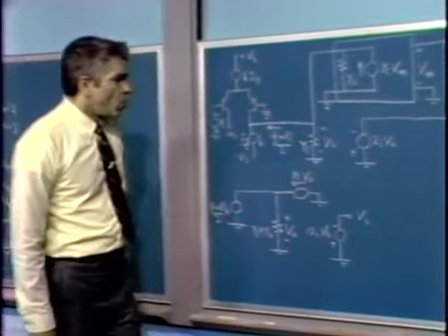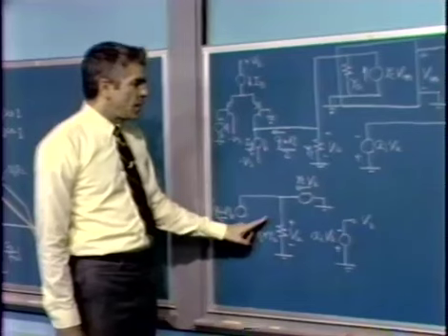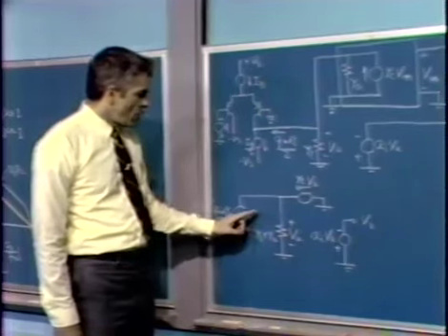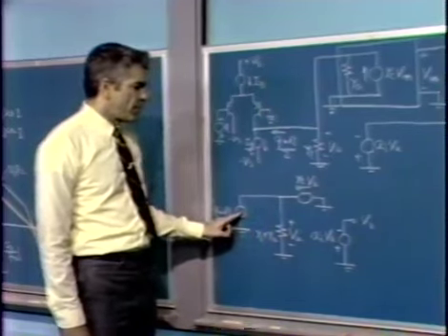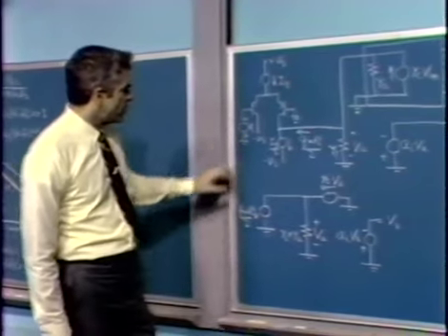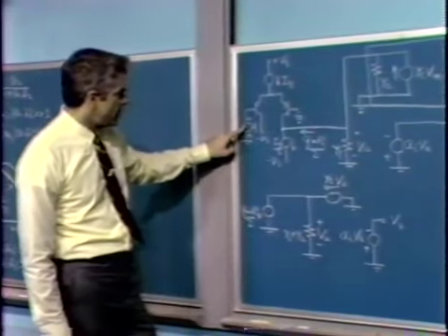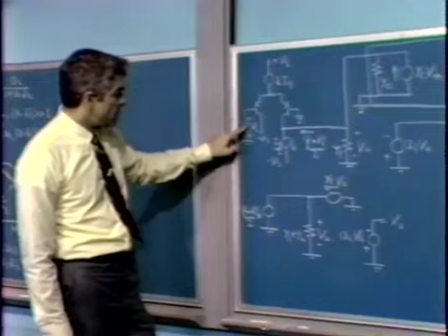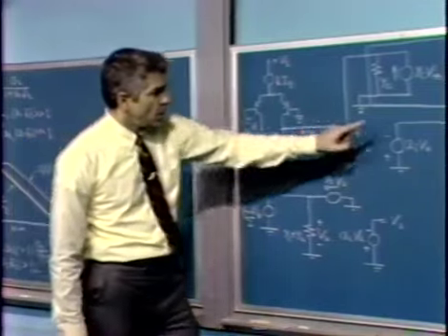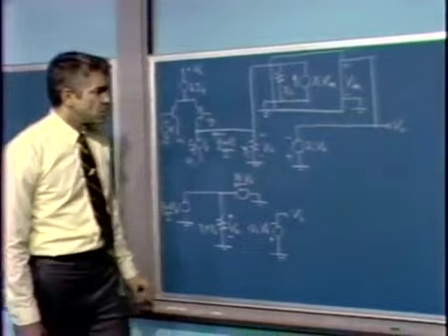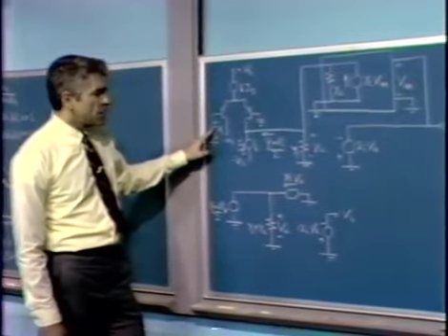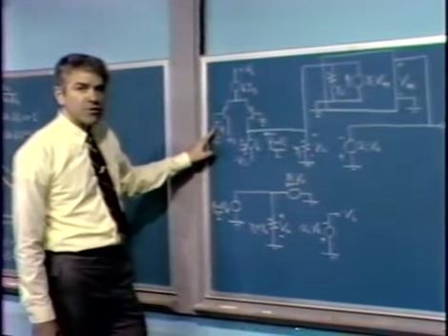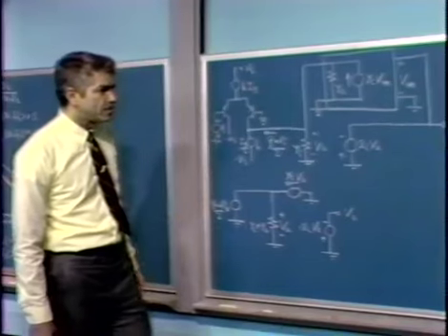We can then use this representation to determine what becomes the open loop transfer function of the operational amplifier. We, of course, have considered the operational amplifier from an input applied to the differential input stage to the output of the amplifier. So this is what we commonly consider the open loop transfer function of the operational amplifier.